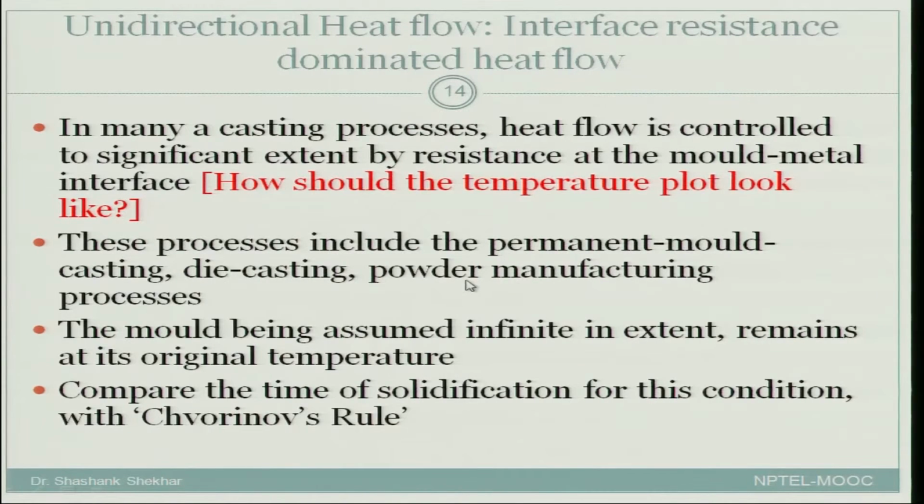But when we are talking about these kinds of processes, we should also talk about the previous one, which was simple sand mold casting. Another assumption there was that the mold is infinite in extent, which means it remains at its original temperature, the semi-infinite condition that we invoked for the previous case. In the previous case we obtained Chvorinov's rule, and here we got solidification time that was different, where S is proportional to T. In the previous case we obtained S proportional to root T.